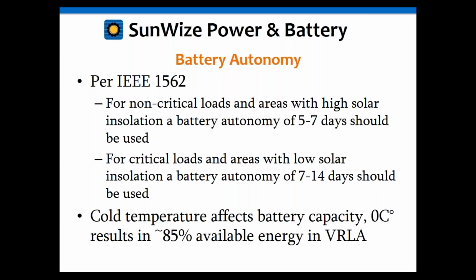And I want to highlight the fact that they don't recommend anything less than 5 days. If you have people trying to do a 2-day or a 3-day battery, they're not following the standard. Again, the industry standard is IEEE 1562. It's the only one out there, and they do recommend nothing less than 5 days. And that's for a good reason.